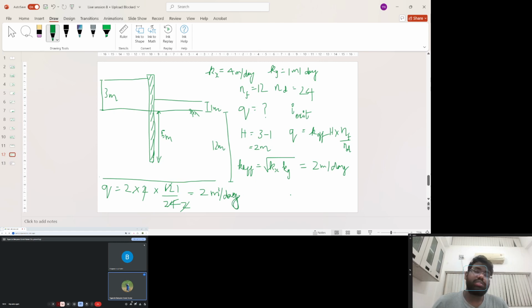So this is the discharge that takes place. Now coming to the exit gradient. So I exit, which is determined as IE, which is equal to delta small h, which is the head drop within one flow grid, by the length of the flow channel.